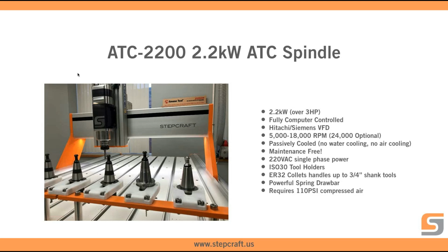It is a 220 volt spindle. And again, it's single phase, so you don't need any special power. It'll work in the average house. Again, the VFD does the conversion from single phase to three phase for the actual spindle itself.